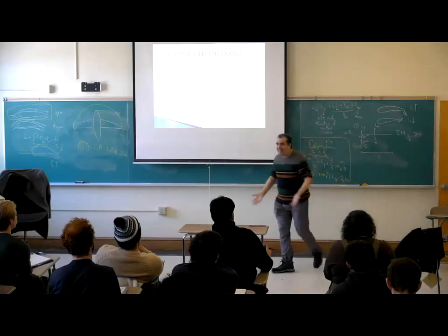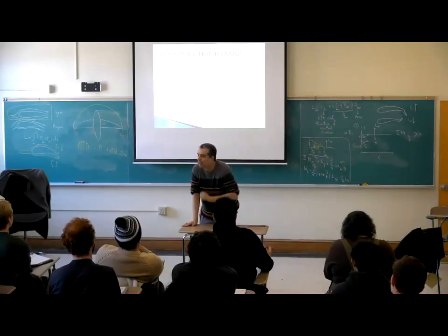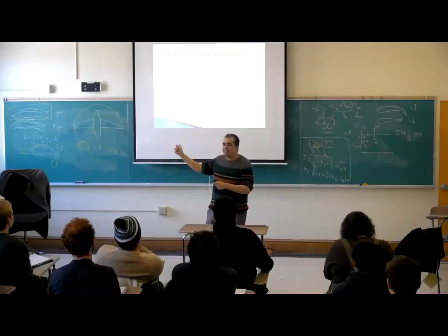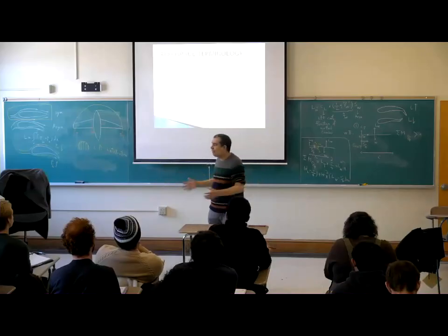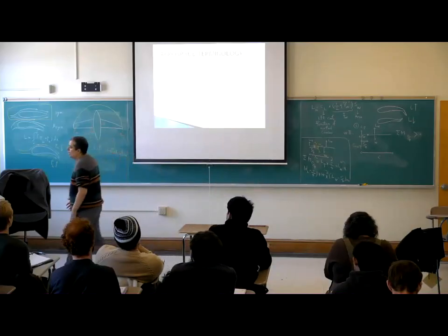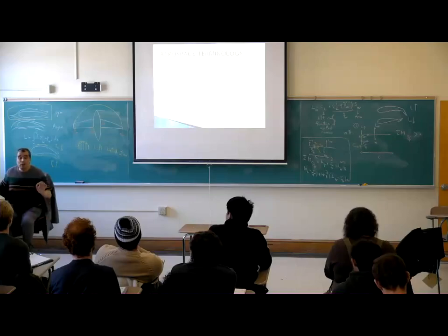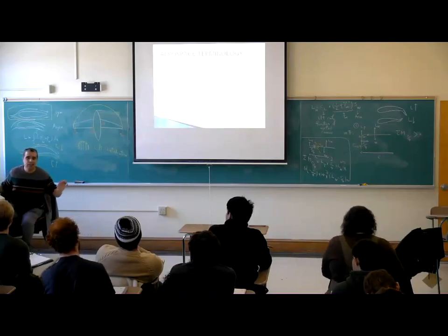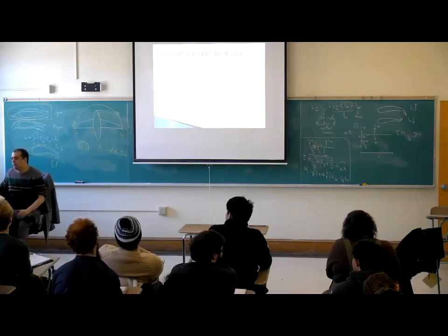You cannot carry as many people as in winter in Canada compared to Orlando. So what should you do? You cannot say, oh, I have 100 free seats and I can sell them. No, you cannot. Or you cannot carry all the baggage. If passengers have a lot of overweight baggage, you cannot carry it. So payload weight is season dependent, not a lot, by maximum 10%, 5%, it depends.